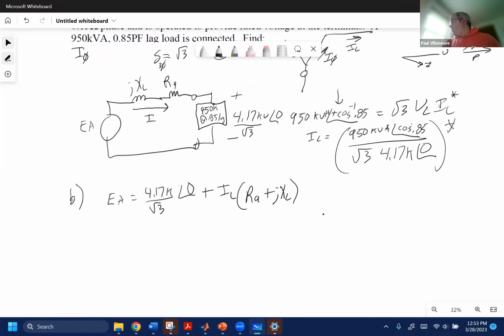If you remember, one of the things we did towards the end of last week was look at this and say, here's our phasor diagram. Remember how we said that if it's a synchronous generator, our terminal voltage is here, and our EA value is going to have a positive delta. So your angle had to be positive. And the other thing that might be subtle is, because it's operating at a lagging power factor, what's the direction of reactive power in or out of the machine?